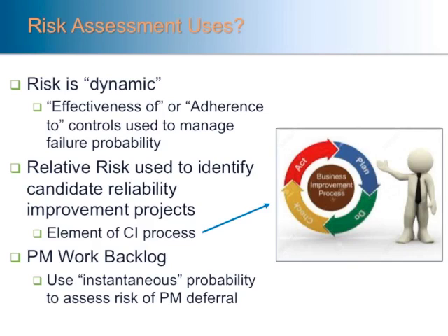And then adherence. We see many instances where controls are in place. There are excellent PM programs and other forms of procedures and strategies. They're just not being adhered to. Relative risk provides us with a method to identify where the gaps are. If you remember that risk matrix again, we would find things that end up in that top right-hand red corner, which is considered intolerable, as candidates for improvement projects. And if it's deemed to be an equipment-related primary causation or cause, then we would feed that into a continuous improvement process for our reliability program.